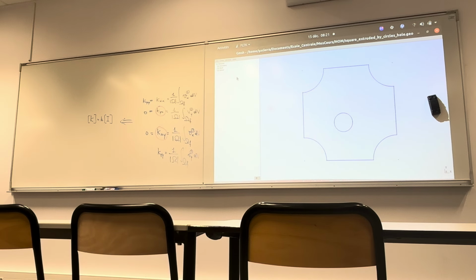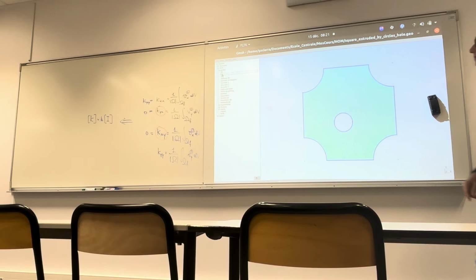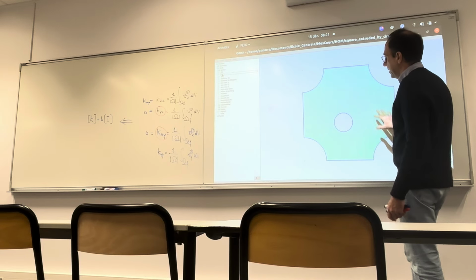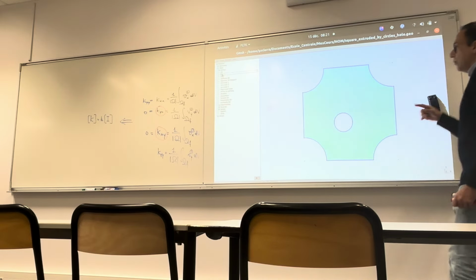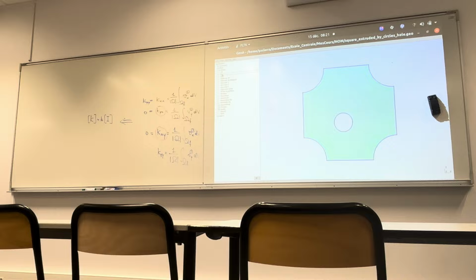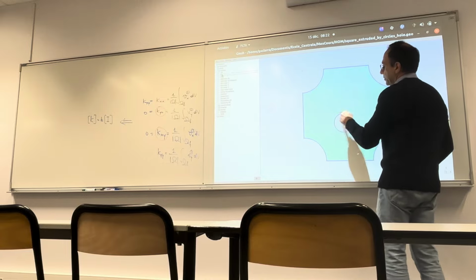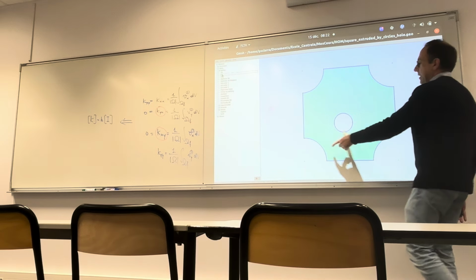This, for instance. So the idea is that you have modified the geo file introducing this additional circle, as an additional curve, and construct now the geometry as the difference between this curve and this curve. Essentially, when we specify the surface, we specify the surface just giving this line. You have to add also that one. In this way, you will generate later the domain like that.